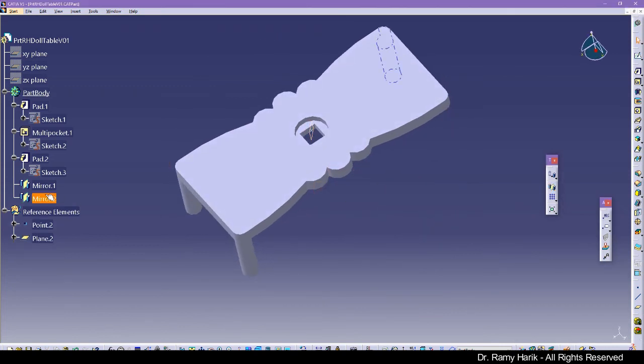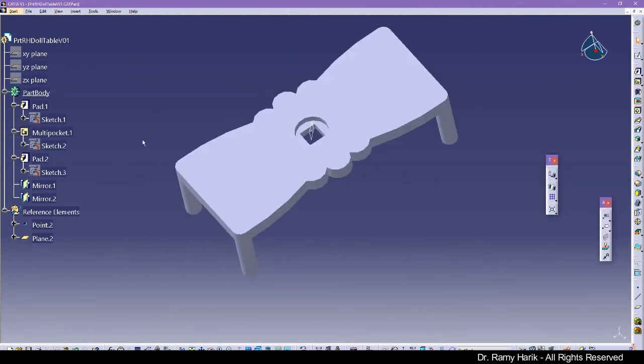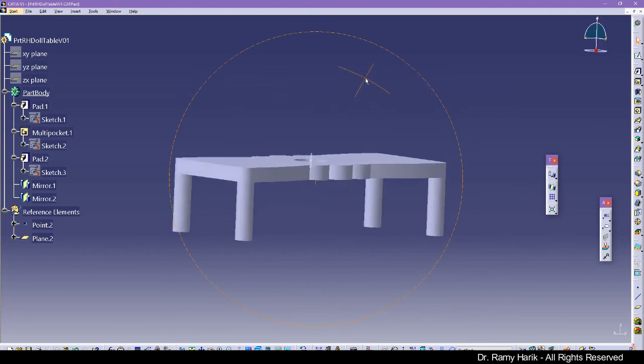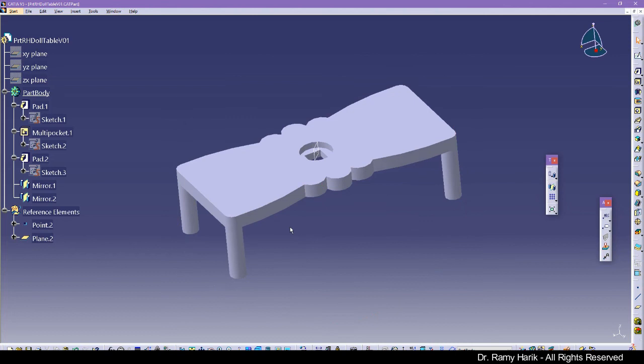So to wrap it up, even though this is not the right way to do it, let's go ahead and do what we just said, which is to mirror with respect to this, and then select this one, and mirror with respect to this, and then close, and then delete the other mirror elements. So I'm going to show you something, and this is why one of my students failed the official certification. Although you don't see it, you have created double volume with those mirrors in here.